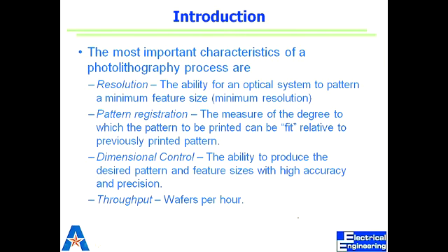Now, both of these things depend on different things. My dimension control has different issues in it if it's not coming out the size you want, right? You know that. The internal reflection, resist, overexposure and underexposure, overdevelopment, underdevelopment can be other reasons than the pattern registration. Which is more difficult, pattern registration or dimension? Think about it. If we go smaller in size, what is more important?